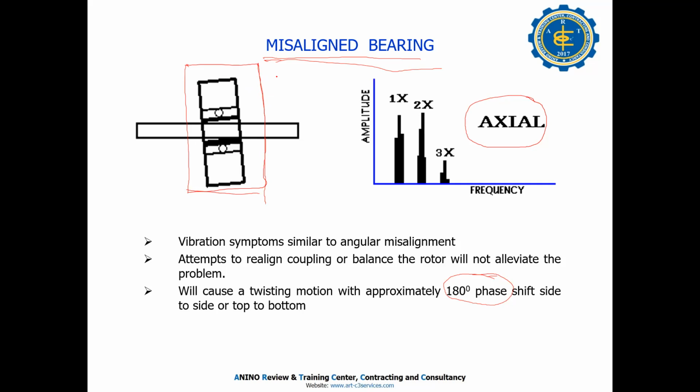We call this plumbness and unlevel. If your bearing or pillow block has no plumbness, the problem will always be present. The bearing is damaged now, and maybe after 1 month it is damaged again because you did not correct the plumbness and unlevel of this bearing.